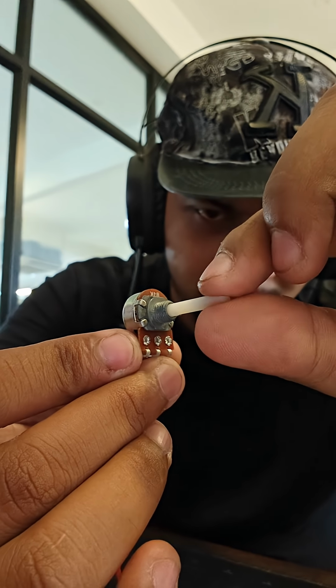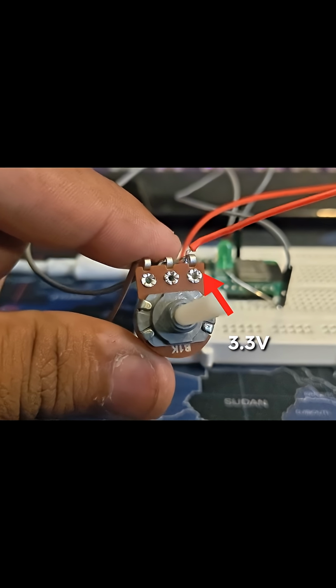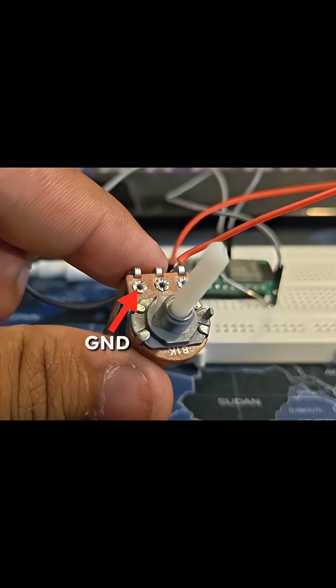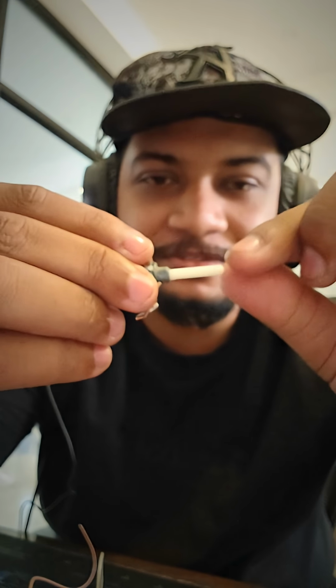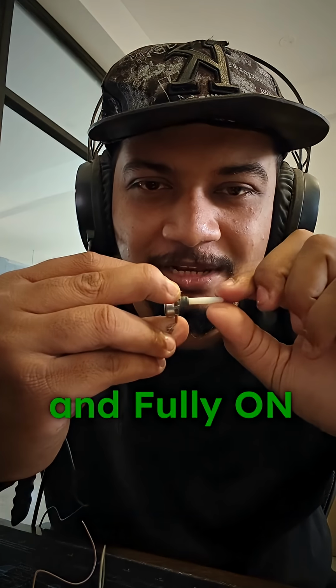Turning the knob changes the resistance, which changes the output voltage. You see, one side is connected to 3.3 volts, the other side is connected to the ground. But you see this middle leg? This is what gives variable voltage between fully off and fully on.